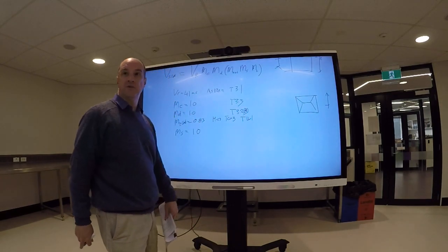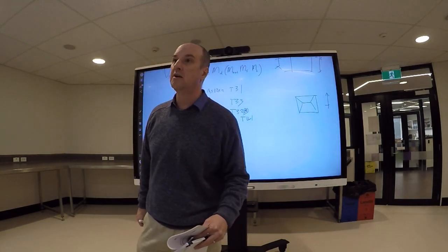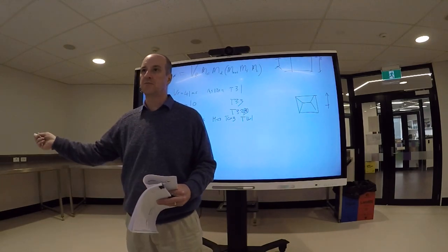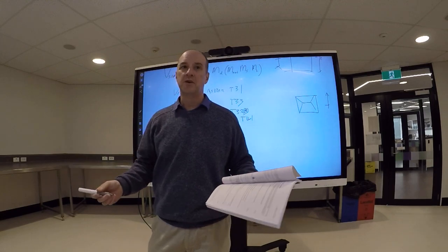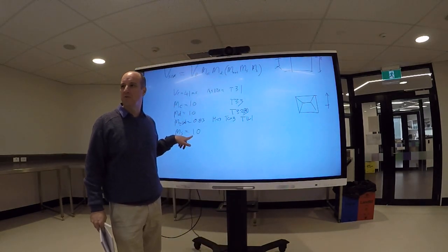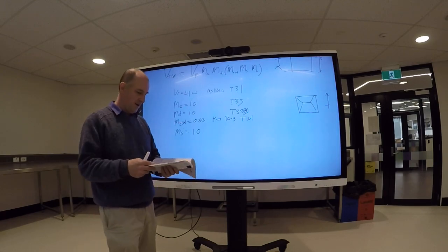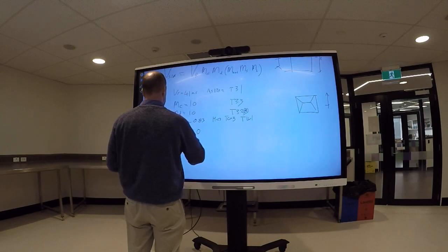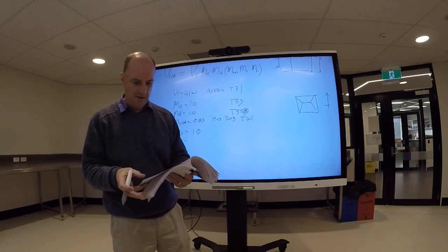You're not allowed to use trees for shielding because they can get cut down. You've got to consider, is the thing that's shielding your structure going to survive as long as your structure, or not? So houses in suburbs, yeah, you get to reduce it. Otherwise, pretty much everything else, shielding is 1.0. And MT is a little bit of a difficult one.